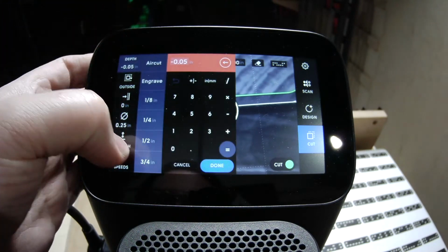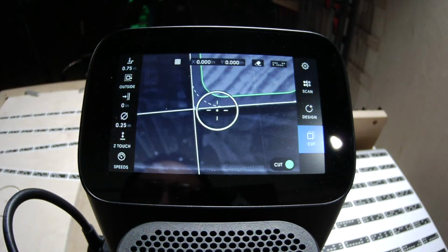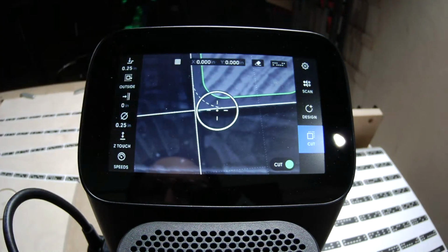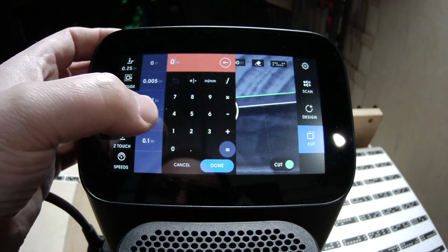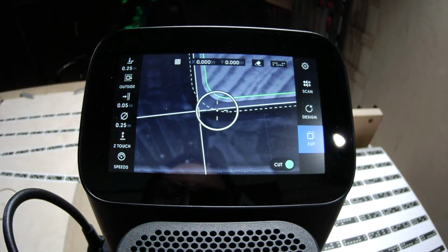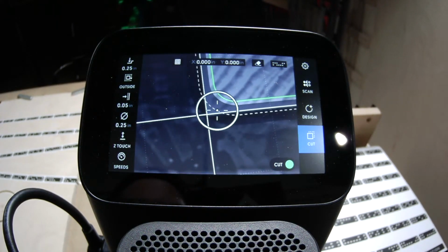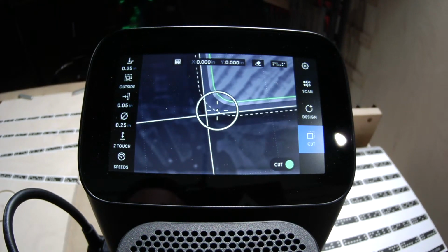Yeah, that sounds great, and I'll narrate the process because I think this is something people may not understand. How do I cut straight to 3/4 inch? Do I do it with one pass? Do I have to do multiple passes? Totally. So as Noah mentioned earlier, the standard depth you cut per pass is the diameter of the bit. That can change some, and Noah's cutting a hickory hardwood right now, so on your first few cuts, start with some plywood or something softer.